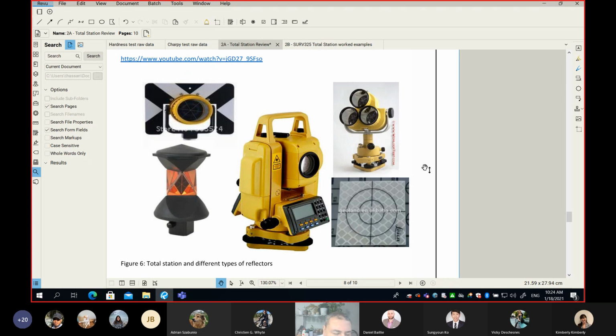For example, he or she has to make sure that the rod is vertical, so looking at the bubble tube. Number two, has to input some information to the total station. Let's say I am on top of a manhole, and then finally, shoot me now. It means don't focus up, just do other things. So hopefully you understand and believe that the bottom left 360 degrees prism works fantastic and is very convenient with a robotic total station.